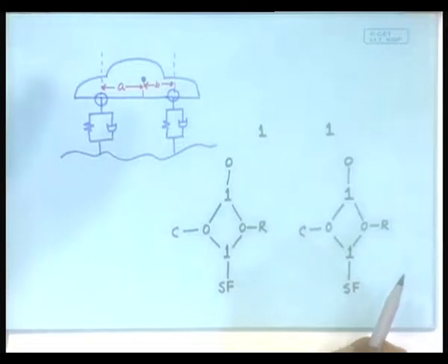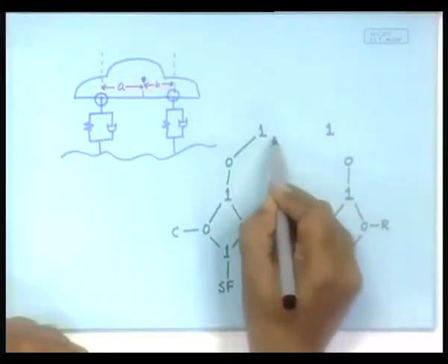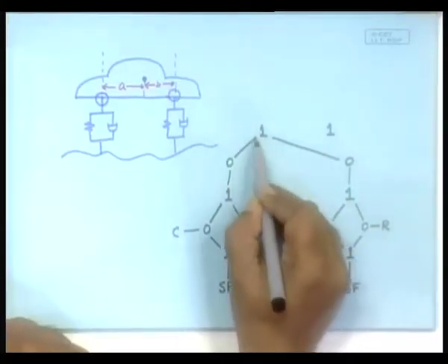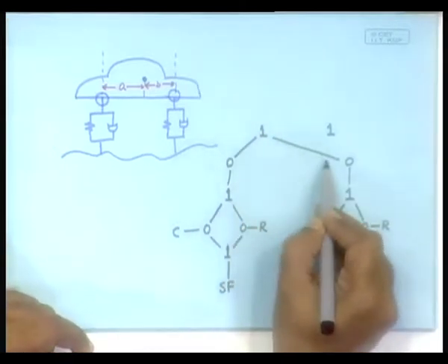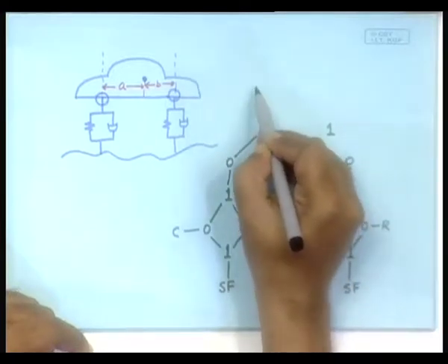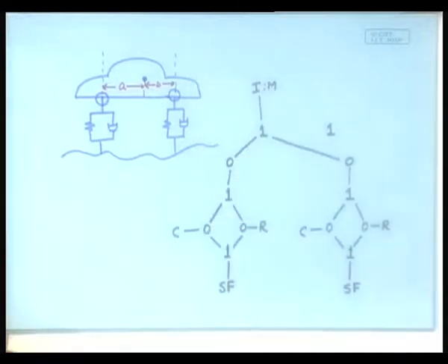Which kind of junction causes the addition of two forces? One junction. A one junction is a flow equalizing junction, but the effort summing junction. So, if you connect it like this, this point and this point, the effort that will be seen here is a summation of these two efforts, fine, and what will be connected to it? It will be the I, the mass. Done.